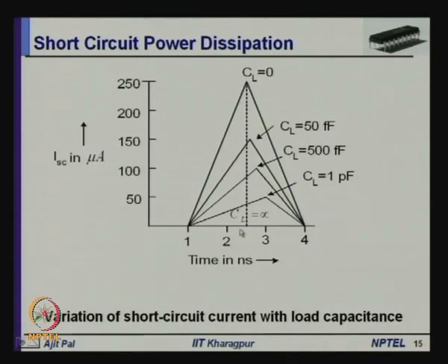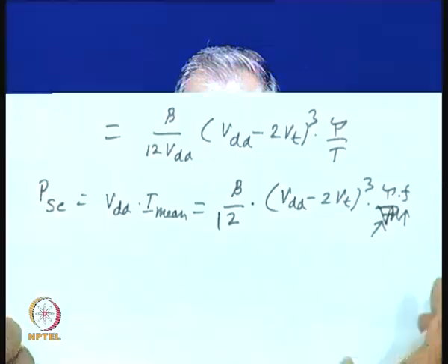However, although the short circuit power dissipation reduces, the delay will increase because of increased capacitance. So, from this discussion, what conclusion can we make? So far as the short circuit power dissipation is concerned, we have seen there are 3 important parameters.